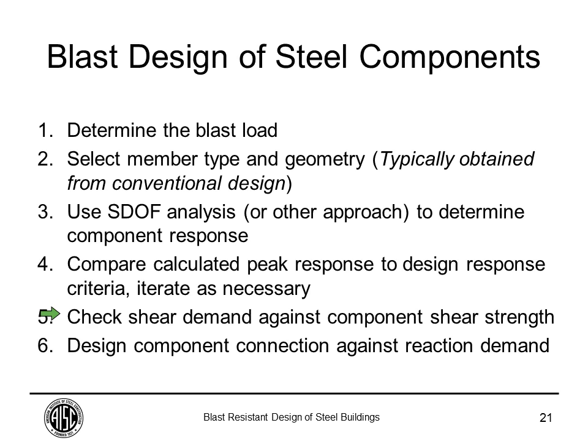You also want to look at shear, make sure that you have enough shear strength and connection capacity to develop that moment capacity and indeed design a ductile member. And then, like I said, you check the connection here at the end as well as the shear against that equivalent static load.